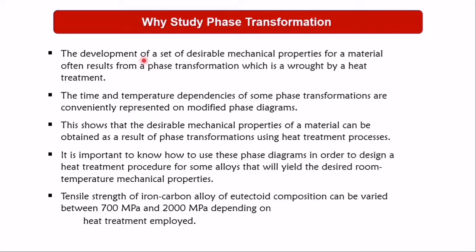You can use quenching, which makes the inside ductile and the outside hard, like having martensite at the surface, and the inside being bainite or pearlite. So this is how we engineer phase transformation. It really helps a lot when you understand this course.